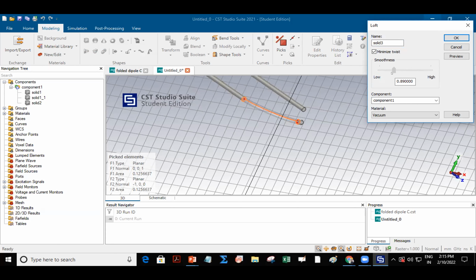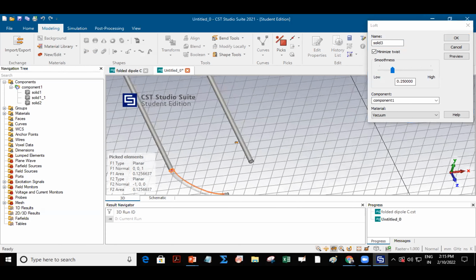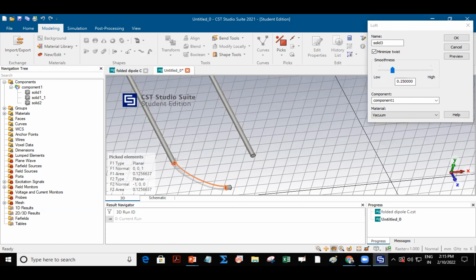Okay, sir. I will check. Sir, it is the radius, right, sir? Well, yeah, radius. Yeah, radius is 3.4, correct. But I mean to say the value here, smoothness cannot be. This is the only purpose why I am doing it now in front of you. Because you see, what we create here in your structure, it is coming as like some closer. So have you selected properly R? If it is R, okay, from here lofting is not from the center. If we see, increase it, preview, it is going like this, right? I don't want this corner. Actually, we want a proper lofting.